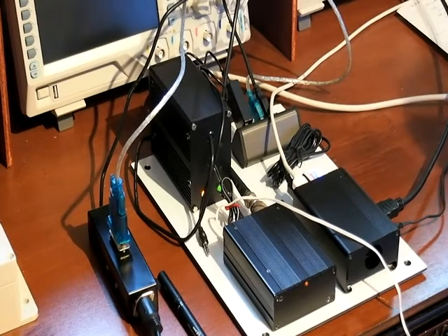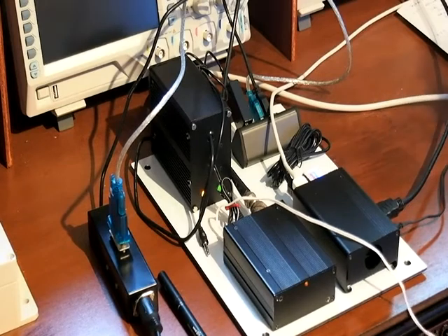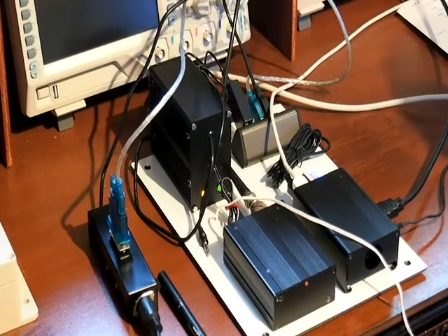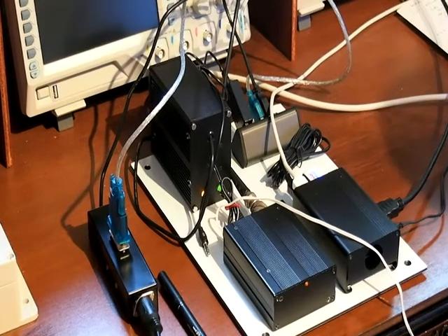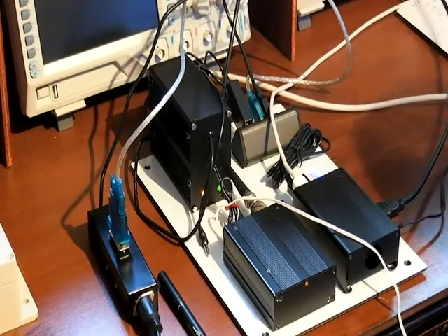With the antenna connected as we have now, there is some noise. You may hear some low frequency tones which are not whisper signals within the bandwidth. The whisper signals themselves can be decoded 30 dB below the noise, and so it's unlikely that we'll be hearing them. But if there's a noise-like signal that isn't too loud, then all is probably well.